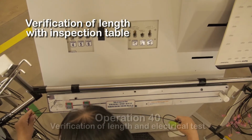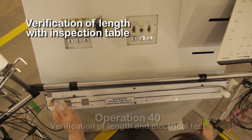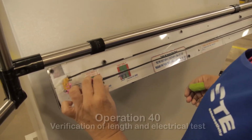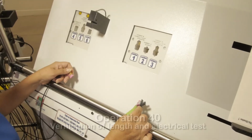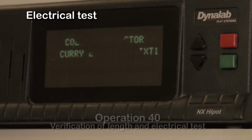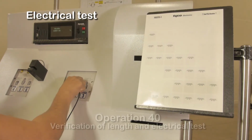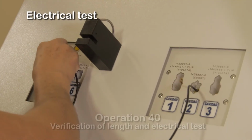Once the part is received at Station 40, the length of the cable is assured by placing the cable onto the inspection board. The connector should be in the green marker zone before proceeding to do the electrical test. For the electrical test, the cable is connected to the tester. The automated tester performs the HIPOT and continuity test to ensure the functional performance of the cable.